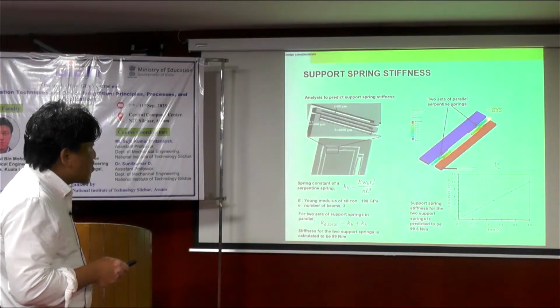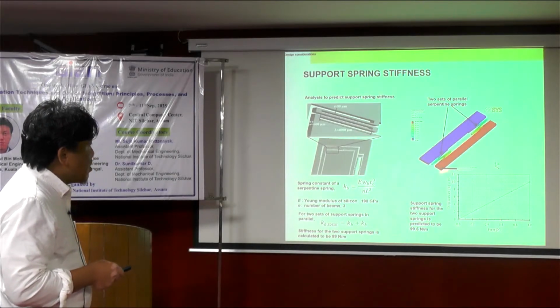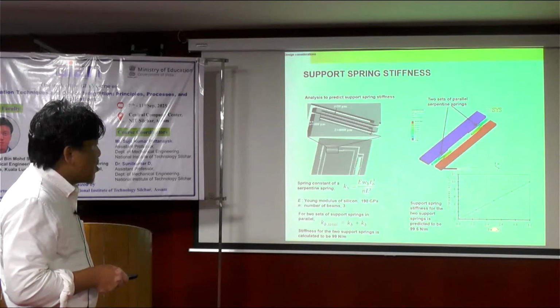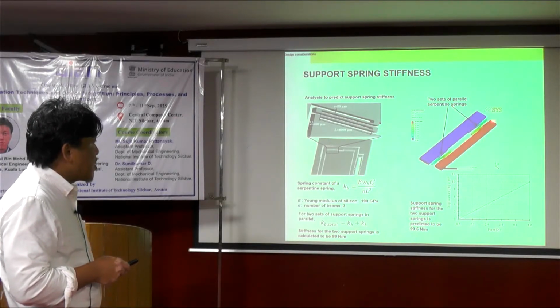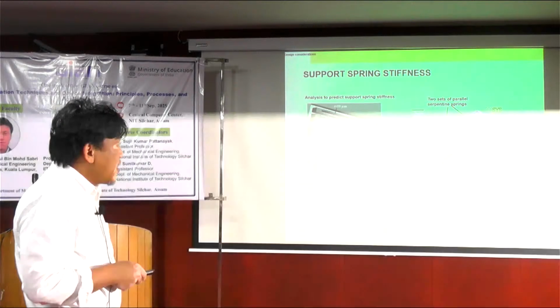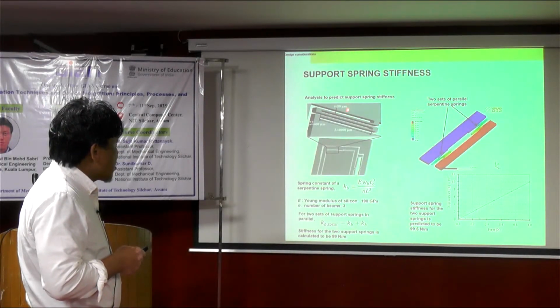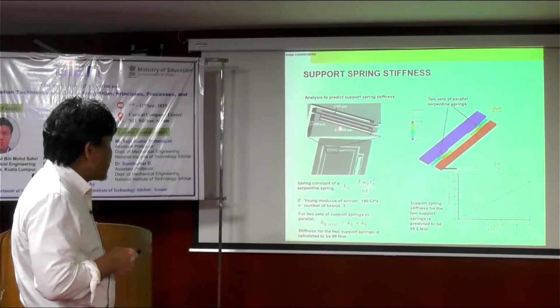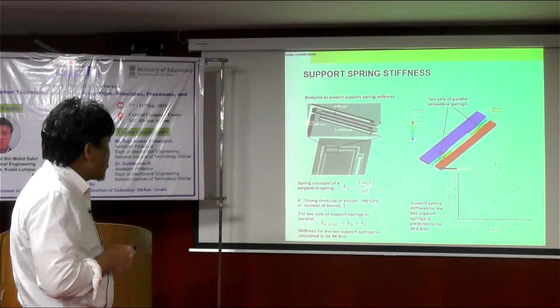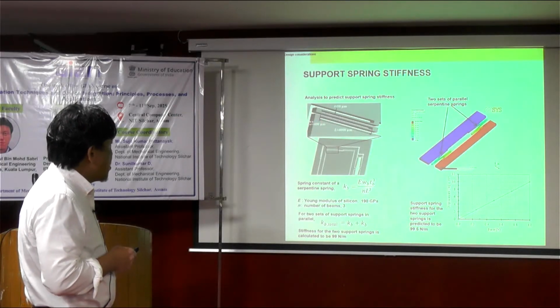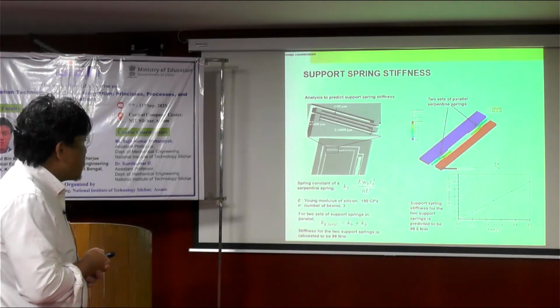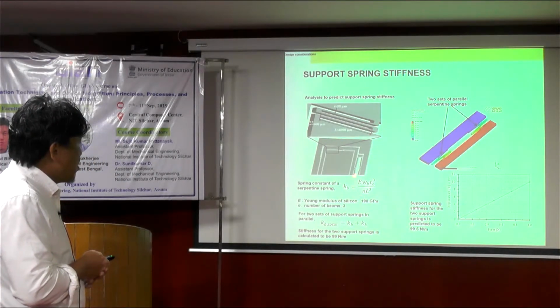So this is also a simulation that has been done in order to look into the force exerted and force required to overcome the support spring. So with this, we can have a proper design of the thickness. Let's say here, with the thickness of 50 micron and the length of 400 micrometer, and this thickness of 400 micrometer, that is where you can get the spring as intended.